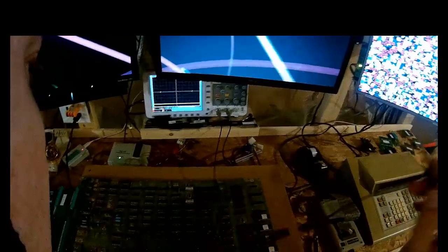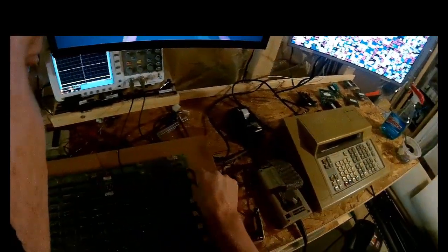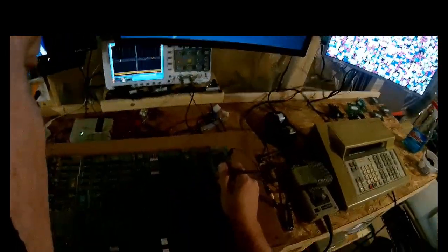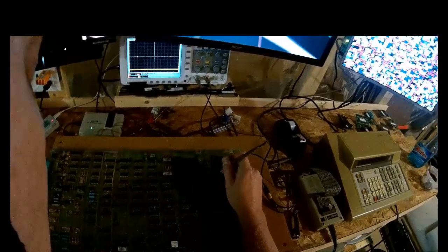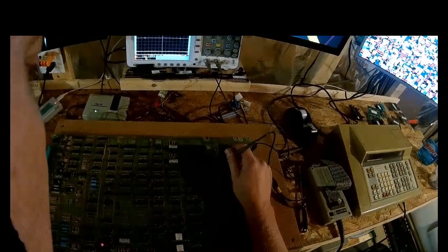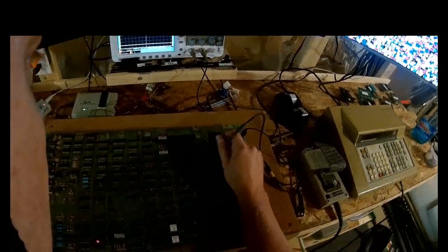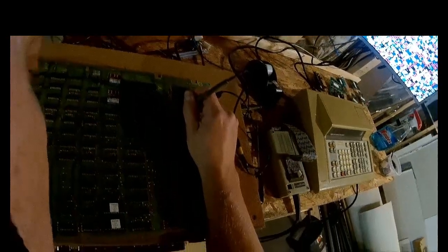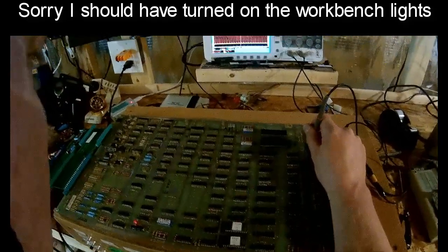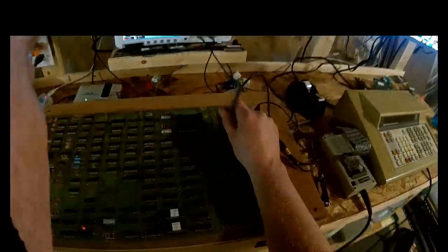And let's check out the O-scope. So we have our O-scope, we're going to ground it, because the next thing we check, once we test the power, is to see whether we're resetting, whether we got a CPU clock. The CPU clock I like to always test first. Actually, I usually do the reset just because on this one it's easier, on the 6502. On the 6502, the CPU clock is 4 back from the top right. So 1, 2, 3, 4. And you see we have 5.1 megahertz. Good. That's what it should be.